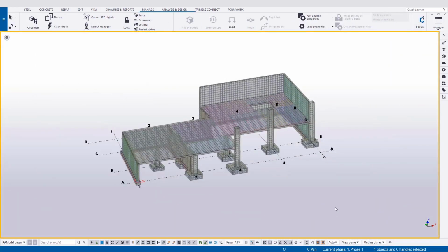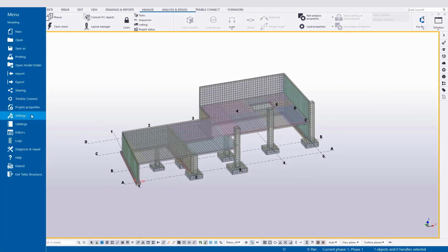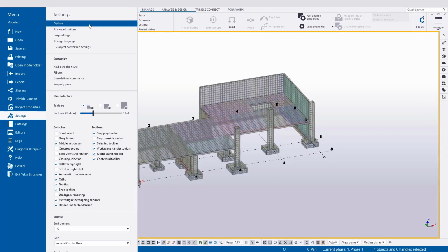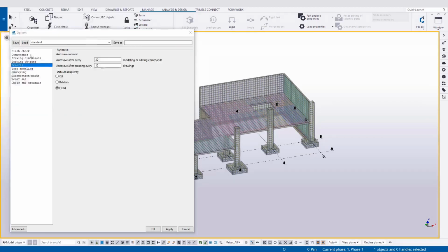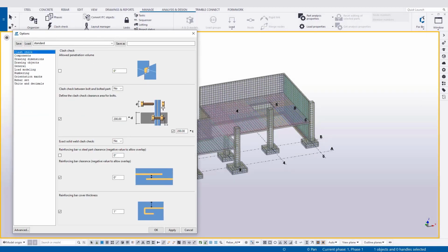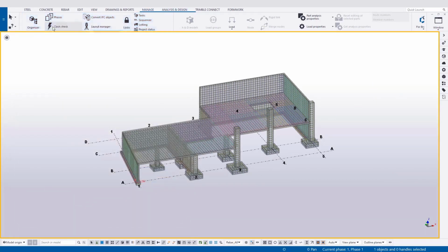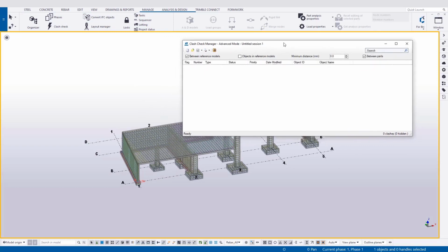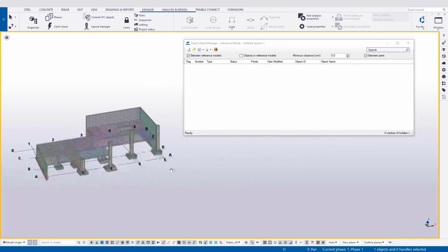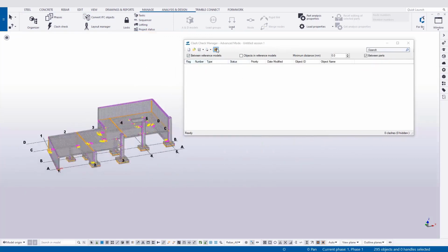The other end of constructability review would fall on a more traditional clash detection. This allows users to identify potential issues based on clearances provided in the model's options. Users can select the model and perform the clash detection and then review the results. You need to choose to either ignore, group, or resolve issues presented in the report. Reports can be saved so they can be worked and reviewed over time.